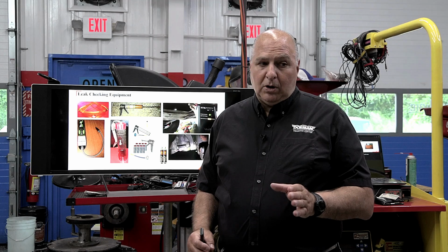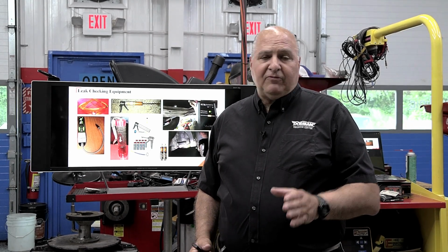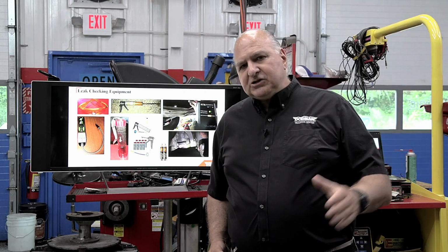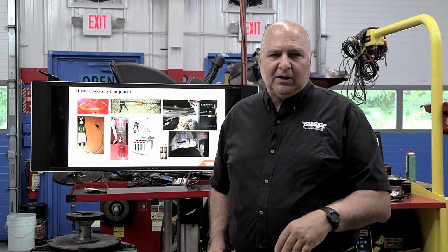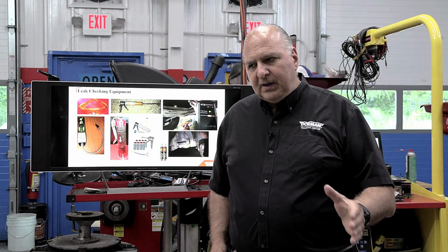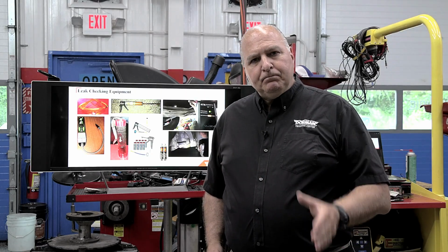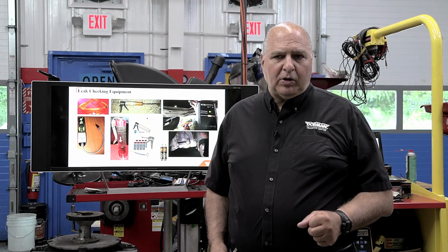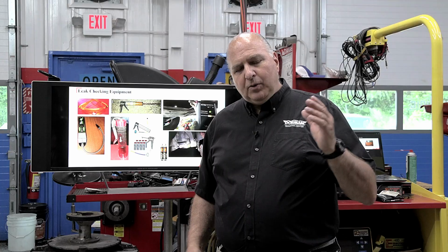Multi-spectrum is important when you buy a light. Why? I'll tell you why. Because you may use a dye, let's say from NAPA, and they sell a particular brand. Then next time you see Whirlpack has a deal on it, you're going to buy the dye there. Well, if it's not the company that made that black light, you may not see that dye. So it's very, very important to make sure that you have a light that is multispectral.